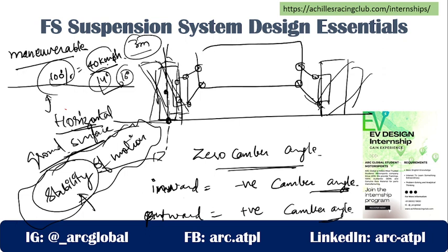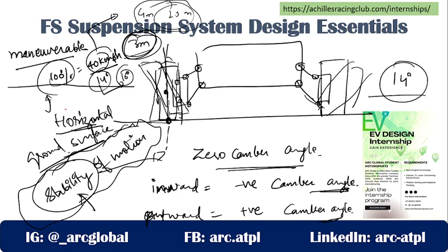But after 40 kmph, this changes. When you want a vehicle to stop at a distance of 3 meters, it depends on the condition. It could stop at 4, it could stop at 2.5. You cannot control it. You can only know the limit. I want to stop in 3 meters, but it can stop within a range of 2.5 to 4, not exactly 3. It could, but I cannot guarantee. I want my vehicle to turn by 14 degrees, but it is not exactly turning by 14 degrees. It can only corner within a range of 11 to 17 degrees. So I can say the maneuver index became 70%.